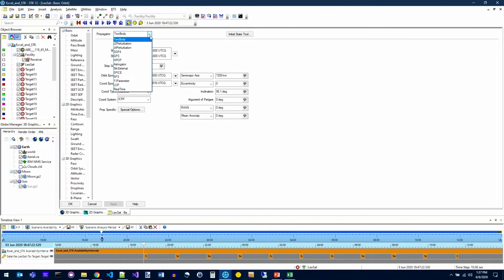So the last type of data files that I want to describe are not just the type that describe the environment, but let's look at the things that define how individual objects behave. So for the space community out there, there's a lot of different types of files that describe a satellite state. So if I drop down the menu here, you'll see something like SGP4. So for anyone that's ever worked with the standard TLE catalog, those individual sets of TLEs are all propagated with the SGP4 propagator. However, if you're looking more at a lot of the astronomical bodies out there, the comets and the asteroids, things of that sort, you'll typically find those published in a SPICE data file.